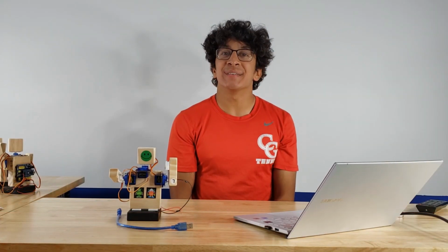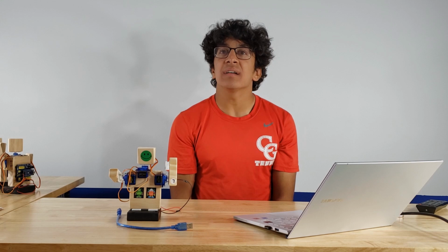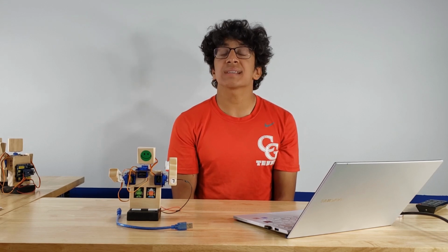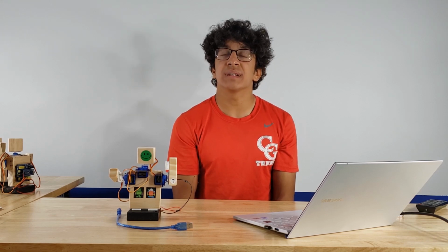That's all. Easy, right? To summarize, the code inside the void setup section first assigns a label to each motor, tells the program which pin on the microcontroller unit that the motors are connected to, and sets the initial motor positions. The code inside the void loop creates the movement of the left arm, the right arm, and the head. You can easily change the range of motion by simply changing the boundary values in the for loop. You can also adjust the speed of arms and head movement by changing the value of delay each time it goes through the loop.